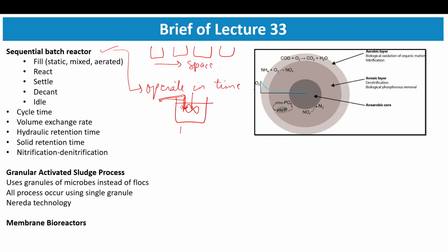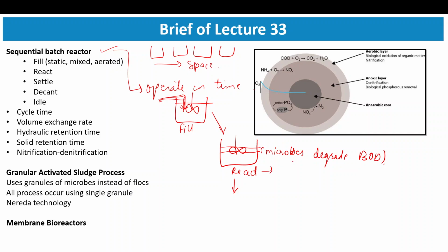Once it is done, you allow the reaction to occur, to interact microbes with the BOD. This is the react stage, where microbes degrade BOD. Next, after the reaction occurs, there will be a formation of sludge. So here you provide constant mixing and aeration.